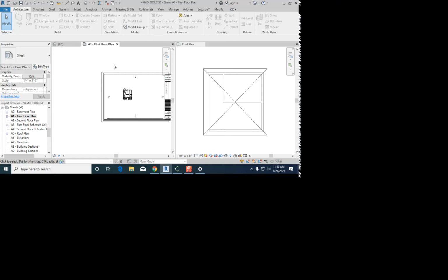How can you, without using the hover tab click, select additional objects like walls? What keyboard shortcut can you use? Control. Okay. What about deselecting? What's the opposite? Good. And then what is an underlay and where would you find it? In the properties bar. Underlay is in your properties bar near the views. And why did we use it today? What does it do?